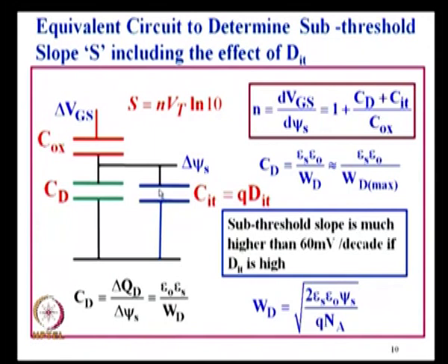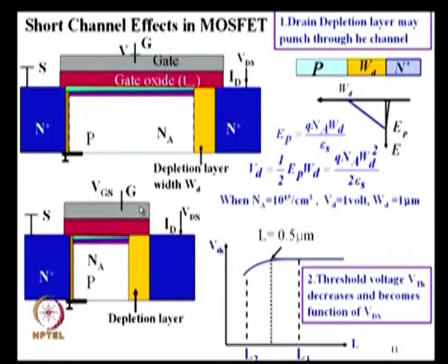But in the case of high K dielectric, it can go 10 to the power 11, 10 to the power 12, unless you use additional passivation techniques. Please remember that this will be a very important parameter when you go to non-classical, non-silicon MOSFETs. Okay. Now, quickly I run through some of the things before I go into some more details.